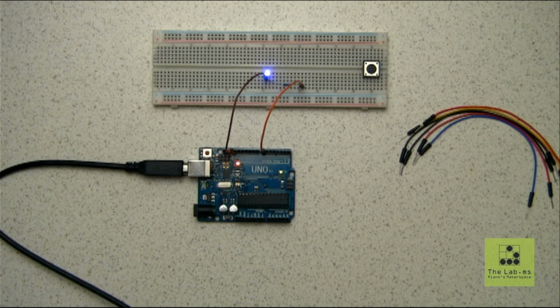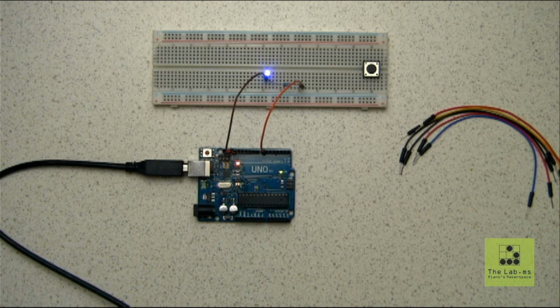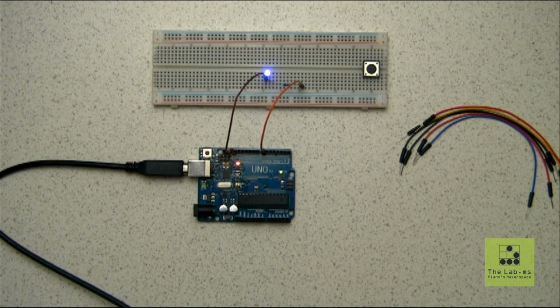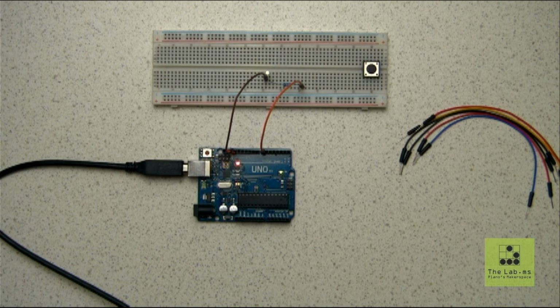But basically, the documentation that comes with some of those breakout boards will tell you where to connect it, and then they'll give you some sample code on how to read the information from that sensor. And then once you've read information from that sensor, you write code that will figure out what to do with it. So in this case, you would read trigger values from the sensor, and then when those trigger values meet certain conditions, like it's greater than certain values, or if it's a digital signal, you'll see that it toggles from 1 to 0 or 0 to 1. When that happens, and you can detect that in software, you can then do something like turn on a light or play the sound like you had mentioned there.